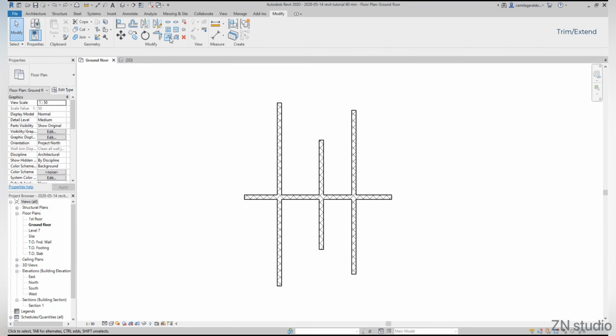In this example, we have 3 vertical and 1 horizontal wall. So I'm going to trim these sections. I'm selecting this wall face as a reference, and then selecting the section that I want to keep, which is indicated with these dash lines. And after clicking, the rest is erased. For the rest, select the reference and the section again. For multiple elements, it's exactly the same as the extended walls. And this time I want to keep the segments above.